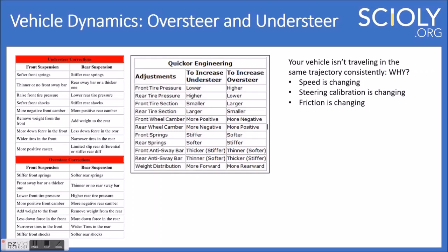So what we found was that we would clean our tires with, it was called belt conditioner, and it would essentially break down the surface of the wheels and make them softer. And it made them a lot more grippy, and you would think that'd be a good thing. It helped in acceleration and everything. But we tended to see strong oversteer. So the radius would be smaller that it was curving in, and the vehicle would end up to the left of the target point.